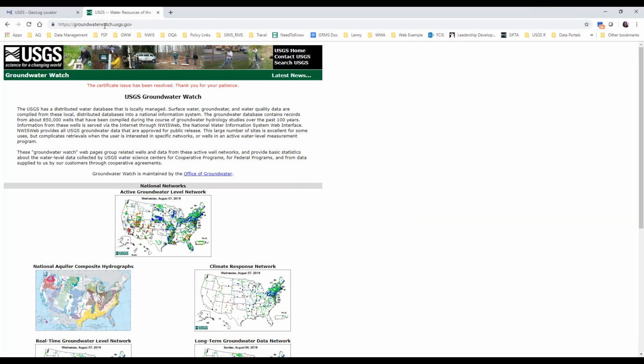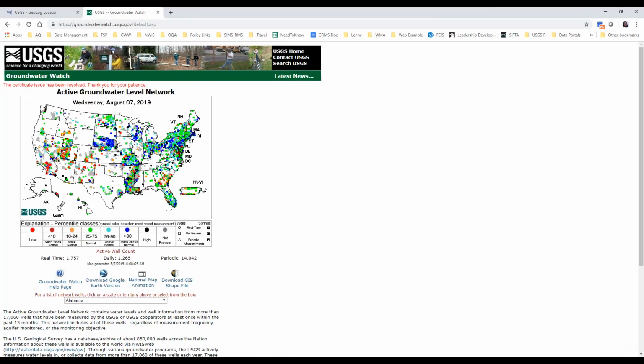If you can use other people's wells, if you can convert, what I'm doing here is I'm also going to our groundwater watch page where it shows how many active wells we have across the nation. You may be in an area where you don't have a lot of wells. So what we would often do is talk to the local folks. Do they have a well that they use for irrigation, let's say, that may not be registered, that maybe you can use for your study? You may have to drill wells to fill in order to answer your question. And that can be expensive, but you would have to plan that in your network design and in the cost of your network.